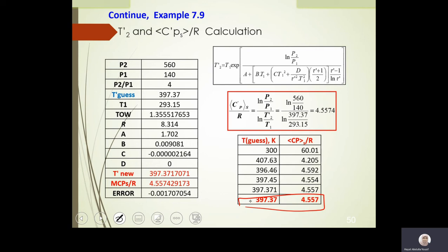So upon integration, CP dT becomes CP delta T, that whole term is constant, and then I have the integration of delta P. So that's basically what you have. That is delta H is equal to CP delta T plus V times (1 minus beta T) delta P. So that's a useful equation. It helps me to calculate delta H actual, and for delta S it is CP ln T2 over T1.